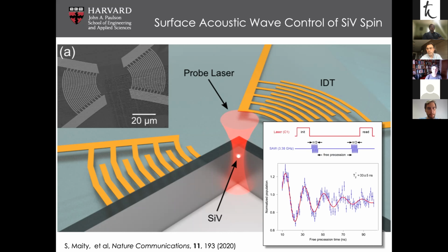We could strain tune, we could actually do mechanical deformation of the cavity. We have also been thinking about pursuing this as well. This can very nicely be done with the isotropic undercut method that I know Daniel, you're working on, and Niana's group. Answer is yes. We have a slight preference for tuning the emitter, and we plan to then address all other misalignments using linear optics, basically. That's what we are thinking. There are other ways to do this, including what Daniel suggests.